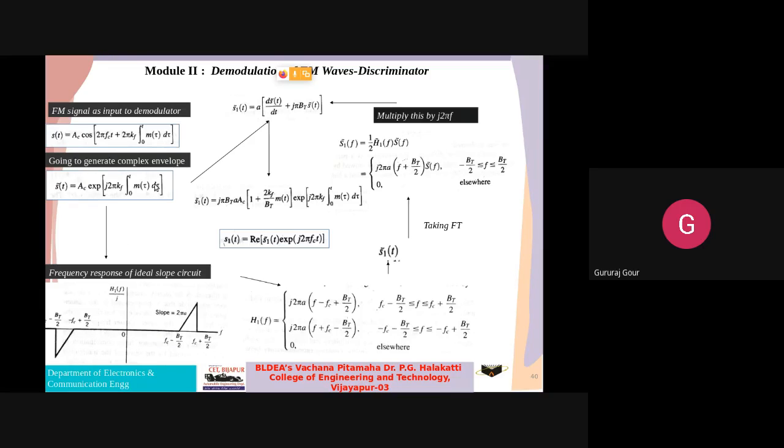So this one I have told you that the FM signal in the balanced discriminator will be having a typical complex envelope, which is assumed because we are using an envelope detector. Similarly, we are assuming a particular phase phi 1 for the FM signal, and a particular phase phi 2 for the VCO output, because these two signals we need to multiply using a multiplier here.